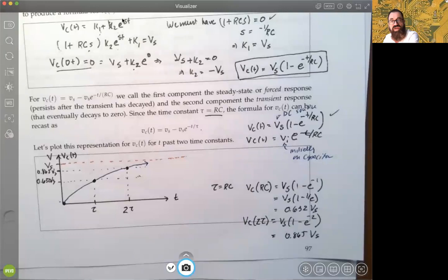So you can control how much you're going to get based on how much resistance you're going to put in, or how much load you're going to put on the system. But notice the intended effect. The intended effect now is to charge up that capacitance, right? And then you could unhook that DC source and then use that voltage that's stored in your capacitance, or switch it off again, right? And it's available to use somewhere else for some other component in the network, okay? So that gives us a good idea of what the use of that resistance could be and network resistances.